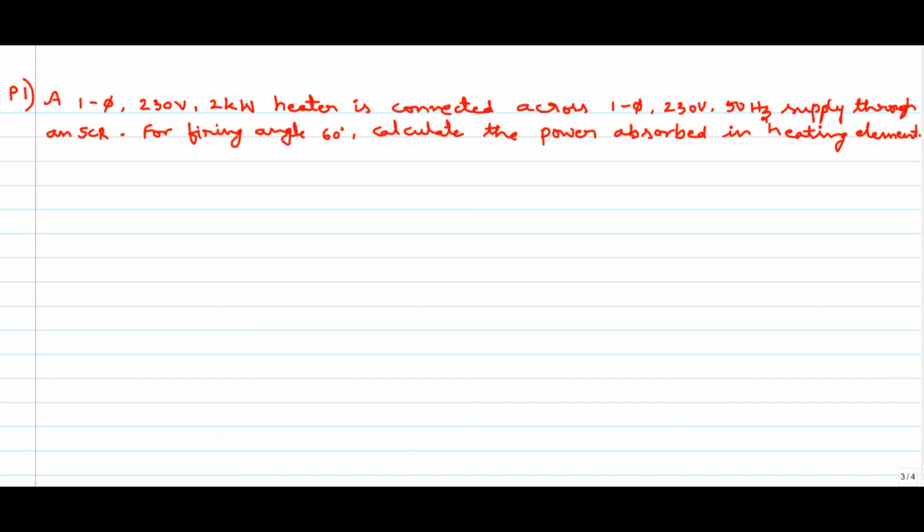Hi friends, let us discuss one problem based on single phase half wave rectifier. So this problem is like this. A single phase 230 volt 2 kilowatt heater is connected across single phase 230 volt 50 hertz supply through an SCR. So for firing angle 60 degree, calculate the power absorbed in heating element. So here half wave rectifier has been used.